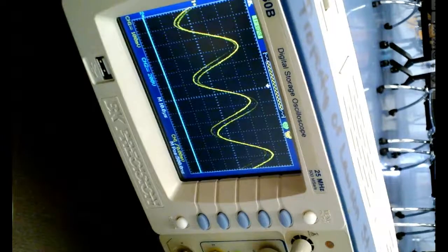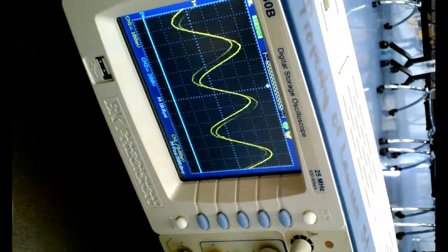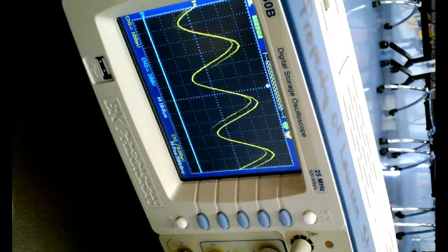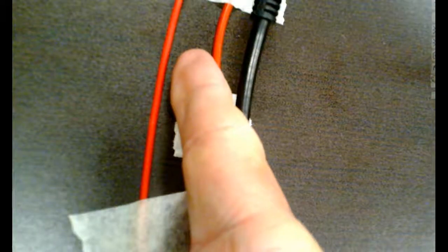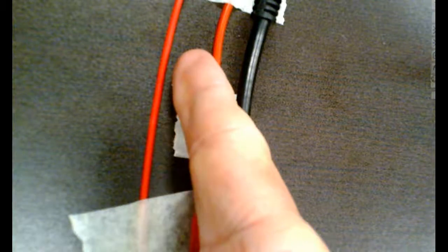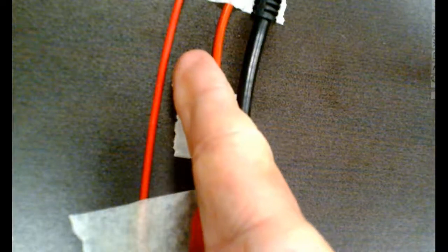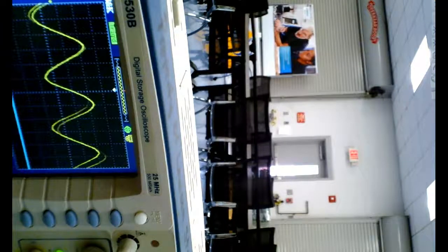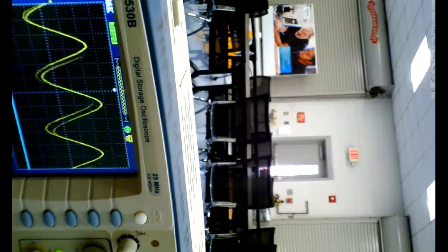So there's a capacitive sensor, right? You understand that? And what can this thing sense? Anything that changes the dielectric constant, which means it's changing that insulator, what I'm putting between the two leads. See, I'm not even touching them, guys. I want to show you this. I'm putting my finger right here. I'm not touching either wire. But what did I just do? I changed the insulator. So now instead of being air, it's my finger, right? You can see I'm not even touching the wires. All I'm doing is putting my finger in the center of them. Then it'll go through me, then it'll induce in me, and I get a change.